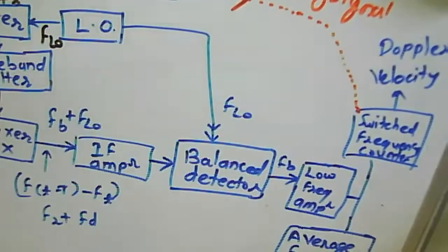So in that case, we are supposed to apply the attenuation at the input side. That's why we need to provide attenuation at a low frequency, but at a high frequency, when we want to apply the attenuator there, the echo signal we have received, because of that large range, will be weak. So that's why we apply low attenuation there, or no need to apply attenuation there.